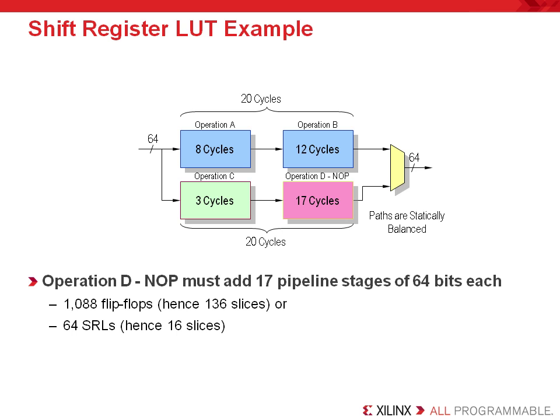Because there are so many registers in FPGAs, pipelining is an effective way of designing to increase design performance. These pipelines can sometimes become unbalanced when too much logic must be generated. It is necessary to delay some of the signals in very typical situations like you see here. One of the best uses of the SRL is to add delay to balance the pipeline.